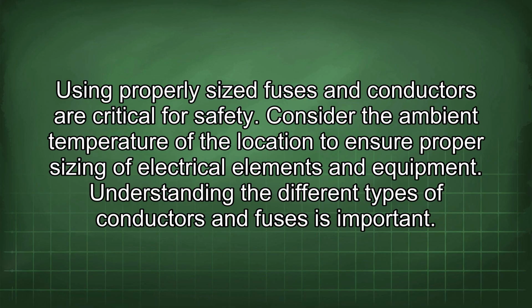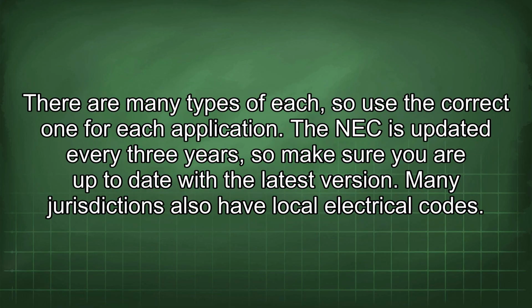Using properly sized fuses and conductors is critical for safety. Consider the ambient temperature of the location to ensure proper sizing of electrical elements and equipment. Understanding the different types of conductors and fuses is important. There are many types of each, so use the correct one for each application.